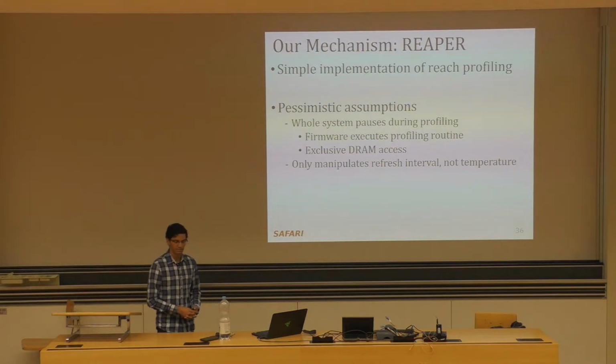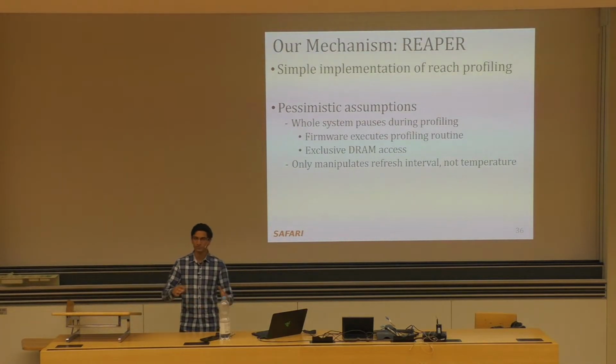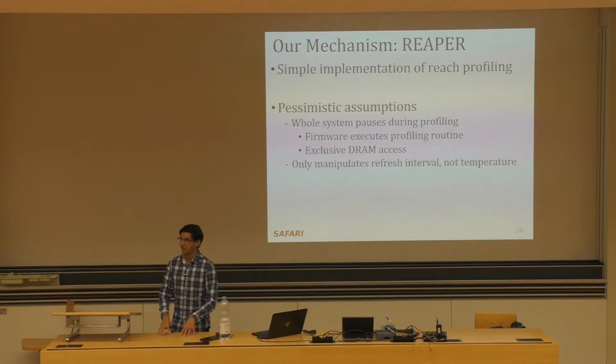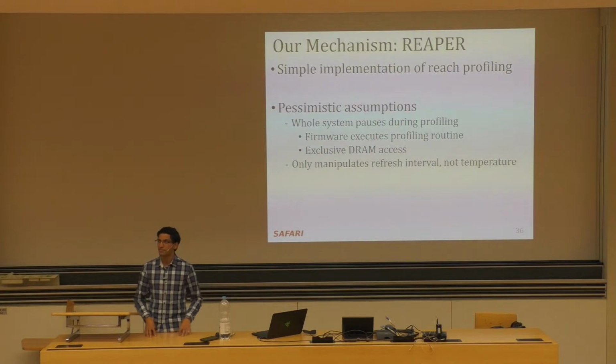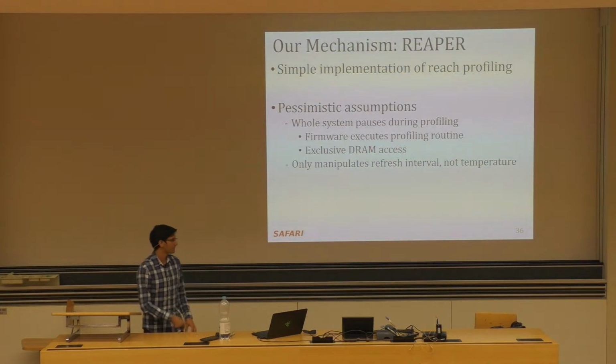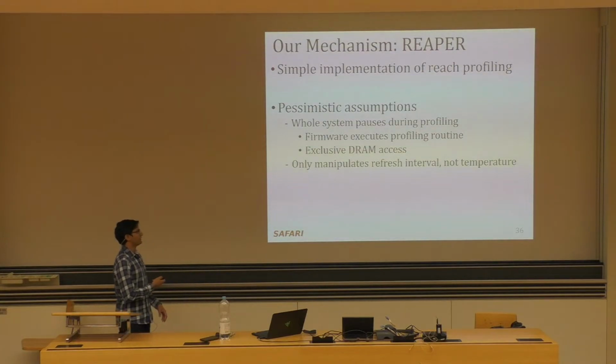And this is very pessimistic because it's essentially saying that whatever is doing the profiling, say some firmware in the memory controller, gets exclusive access to DRAM. And any applications that need to access DRAM are just excluded from the DRAM until profiling is completed. The second thing we assume is that the REAPER only manipulates the refresh interval, but not temperature.